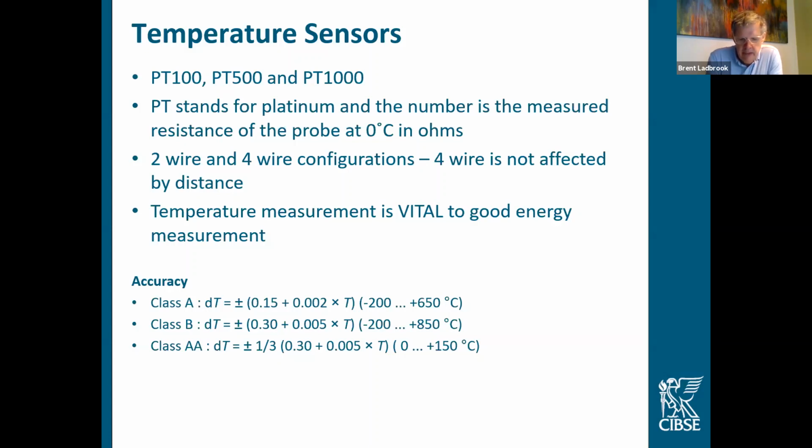So it really at that stage does not matter how accurate you think your flow sensor is or how good you think your calculations are that you maybe wrote using some formulas you found. Your potential error is pretty big, 16%, and no one would ever want to purchase a thermal energy meter with a 16% uncertainty, that's for sure.